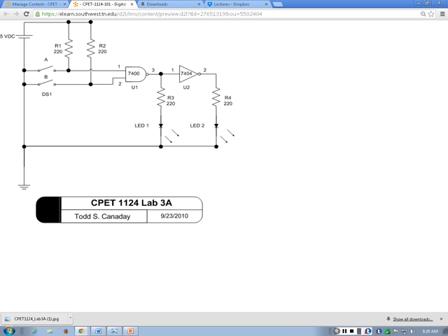For working correctly, every single row has to be right. If something is not working, the whole circuit is not working, somewhere something is wrong, we have to figure it out, and there is a certain way of figuring it out, okay? We'll do it in the next step to show you how to debug the circuit. That's really important. Because once you build the circuit, it may not be working, something may be bad, resistor may be bad, connection may be wrong, pin may be wrong, IC may be bad. How do you know it? You cannot know it just by looking at those, okay?